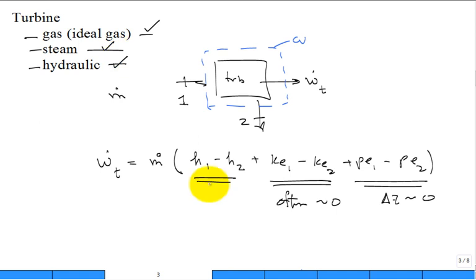How do you have a high enthalpy? Think about enthalpy. It's U plus PV. Well, I'd like a large U. Make it hot. And a large PV, make a large pressure. So if you make it high pressure steam, the steam has a very large pressure as well as a large specific volume. So especially for a steam turbine, this term right here can be dominant.